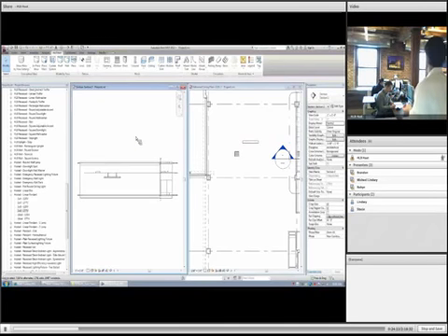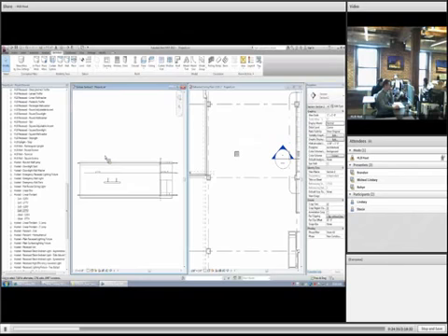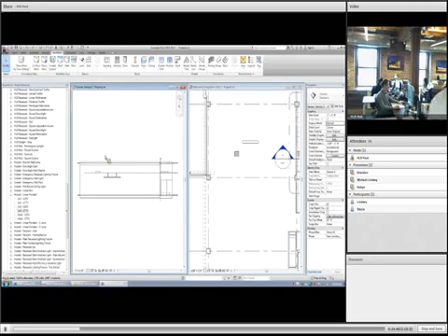If you're placing fixtures and you're not seeing them where you would expect, go into properties, make sure that they're at 0 or that they're not 8 feet above where you're trying to place them. In the case of this pendant, watch what happens when I change the offset. See, it pushes itself off. So it is movable off of that work plane, and we just need to be conscious of that.